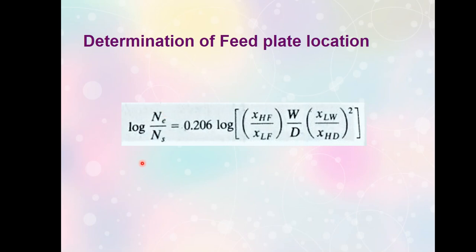And if you are to construct an algebraic equation from that ratio, we can say that Ne, based on my sample, is equal to 10 Ns. If the ratio of these two, for example, is 10, that's just an example, then Ne is equal to 10 Ns. In your total number of stages, let's say it be 50, then that should be Ne plus Ns equal to 50.